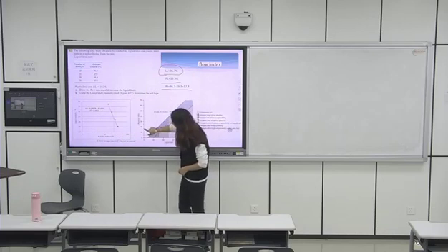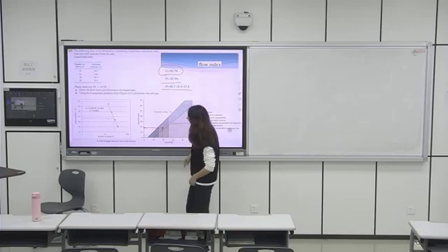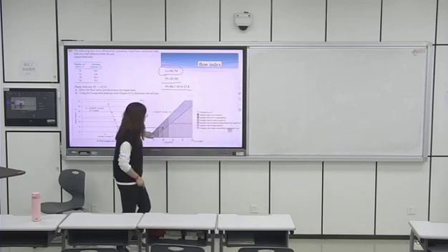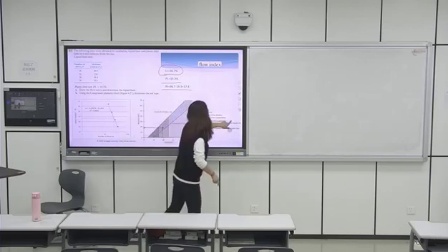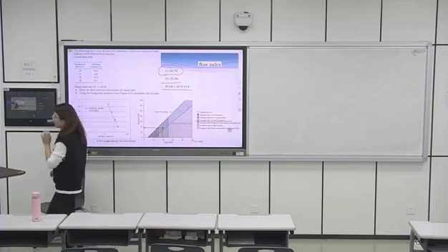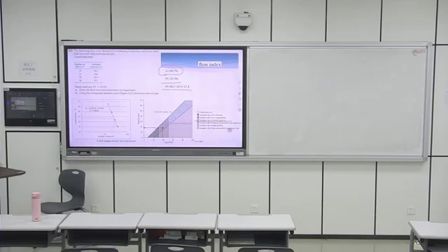17.4 is maybe around here. And this is 36.7. So the soil should be located in here. Let's see. For the soil, this is inorganic clay. This is the first one, second one, third one. The third one is inorganic clay of medium plasticity. So this is the soil type we determined, right? So this is the answer for this question.